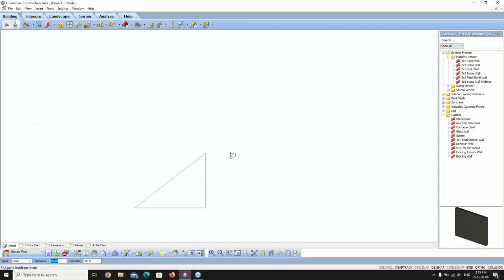And then we're just going to move our mouse up in the 90-degree direction. Again, notice that the closed polygon is now formed. So I'm seeing a bit of a triangle look to our design. With my mouse moved up in the 90-degree direction, I'm just going to type in 10 feet and press enter. I'm going to move my mouse to the right again in the 0 direction, and we're going to go over 5 feet, enter. I'm going to move my mouse upwards, again, 90-degree direction. We're going to type in 20 feet, and I'm going to move my mouse all the way to the left.